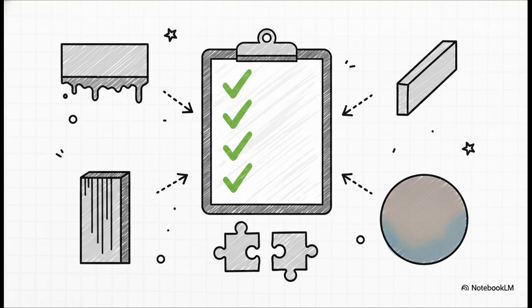This is the actionable part. We're handing you the ultimate first article inspection tool to hold your supplier's feet to the fire. Next time you get a sample, run it against this rapid-fire audit. Do you see hardened dross attached to the bottom? They messed up the cutting speed.